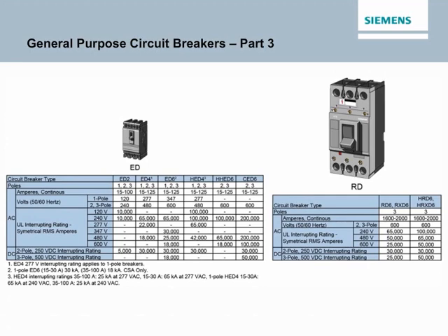These designations also coincide with label colors. Standard circuit breakers have a blue label, breakers with H and HH prefixes have a black label, and breakers with a C prefix have a red label. FD, JD, LD, LMD, MD, ND, PD, and RD circuit breakers, including breakers with H or HH prefixes, are designated as a complete breaker unassembled with lugs, indicating that they include a frame, interchangeable trip unit, and line side and load side lugs in separate packages. For applications requiring non-standard lugs, separate lugs must be ordered.